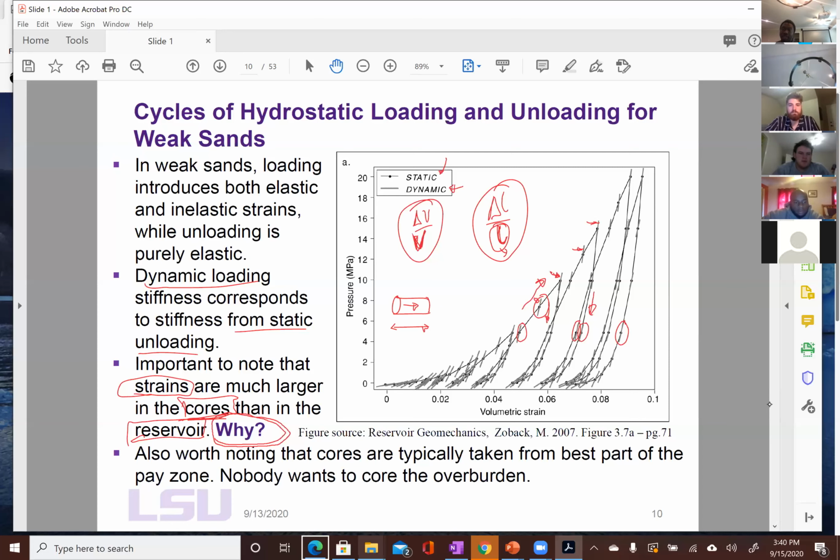And that's why the assumptions in the Cauchy stress tensor make sense, right? And what's the assumption in the Cauchy stress tensor? Small deformations. Yes, small deformations, and the deformation is related to the strain. The strain is a measure of the deformation. But size doesn't have to do with anything. If something gets 5% longer, you can't necessarily say it got 2 inches longer. It just got 5%. And that's what strain is kind of measuring.